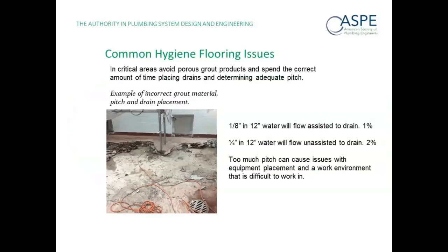And one of the ways that we try to get rid of water effectively in a lot of different areas, whether they be healthcare, life sciences, food facilities, is to effectively, in some cases, pitch the floor to get the water out or evacuate the water to the drain, and have the drain be a hygienic system as well, to remove any types of fluids as quickly as possible.